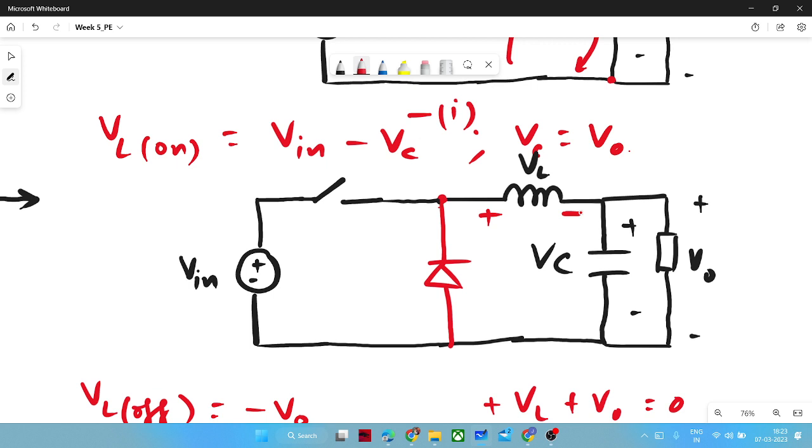That is the amount to which the inductor voltage has risen during the on time of the switch. We should make sure that the voltage has reached a value equal to the output voltage plus the diode turn-on voltage, so that when you open the switch,